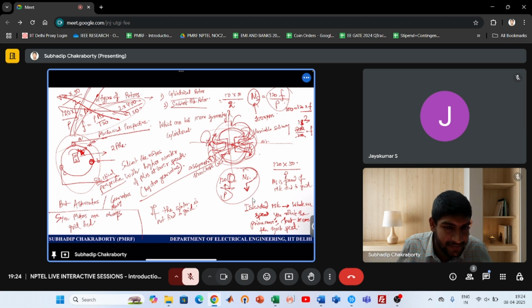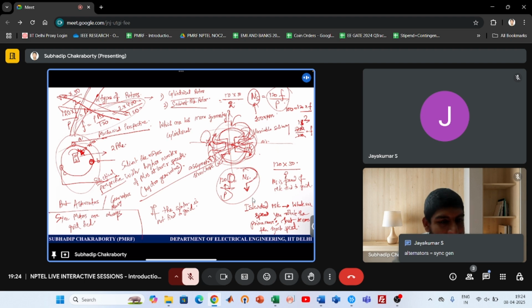It is a diesel generator. So that is nothing but a synchronous generator. Okay. So that is not tied to the grid, because when it functions, when the power goes away, it is islanded. So whatever speed you rotate the prime mover, that itself is the synchronous speed. But we generally rotate such that the DG set also generates 50 Hertz. That is a different thing. But you must understand, alternator means synchronous generator, and generally diesel generator sets are also synchronous.